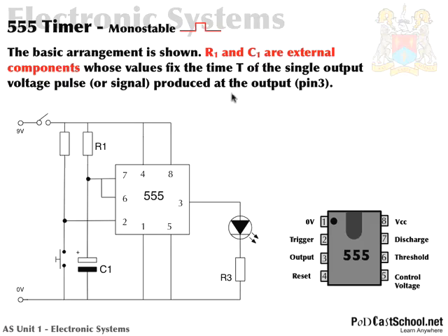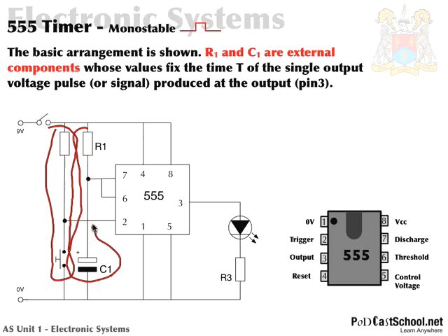You can see that the configuration that we've got here, we've got basically 2, if you think of them as potential dividers. So here's one potential divider, even though it's a switch, don't worry about that. And here's the other. Bit wonky. Don't forget, you can think of a switch as a potential divider. It really is a resistor with a very high resistance, sometimes almost infinite, and a very low resistance, sometimes almost infinitely small. Okay, so you can think of those as two potential dividers.